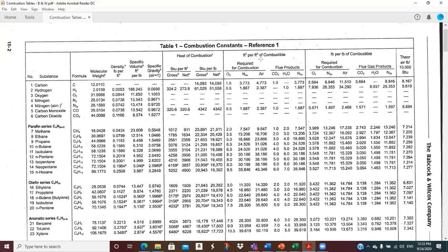That's the heat input that I have to put in the natural gas, in the methane. Each cubic foot is 1,000 BTUs, so if I divide this by 1,000, I'll get cubic foot of natural gas per hour. That's 312,500 cubic foot per hour of gas.